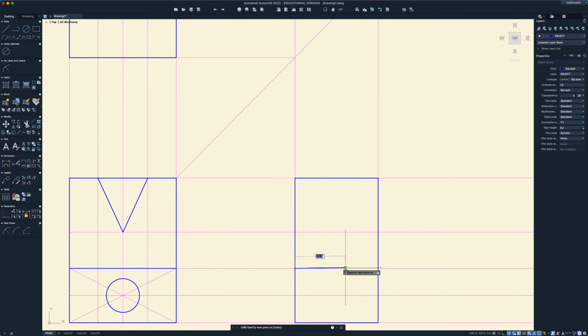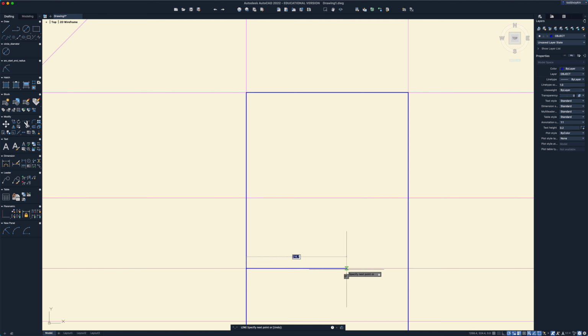Now this is where you have to be careful, because sometimes when we have this nearest on, it doesn't actually snap to that line. It's snapping to this nearest, and sometimes if you're down a little bit, it'll actually make a crooked line. So I know that that's at 0 degrees. So I'm going to type 175 tab 0 enter, and that made sure that it was perfectly horizontal.